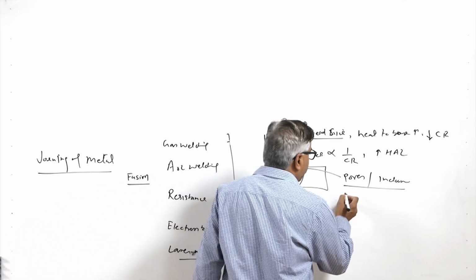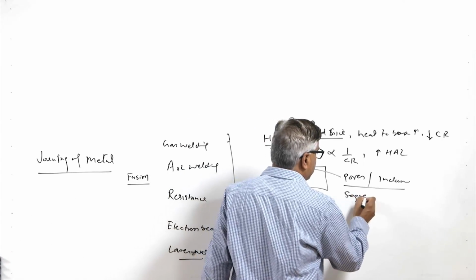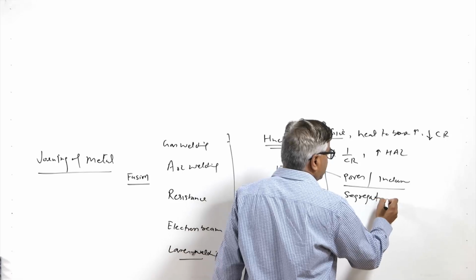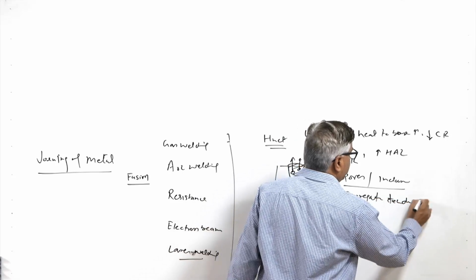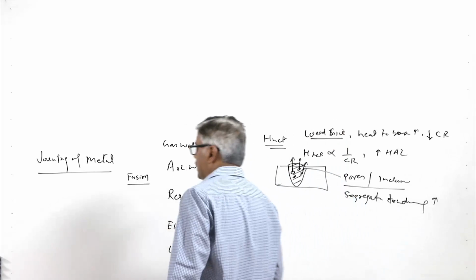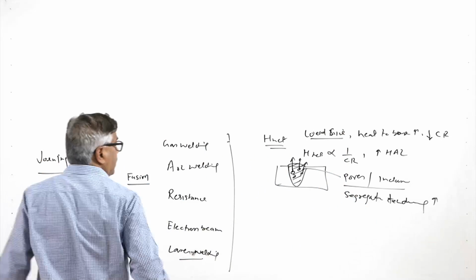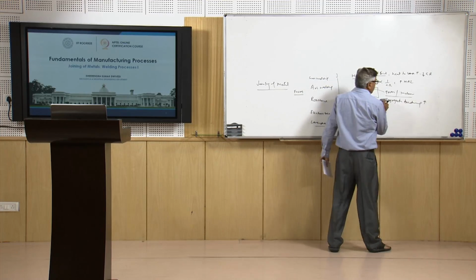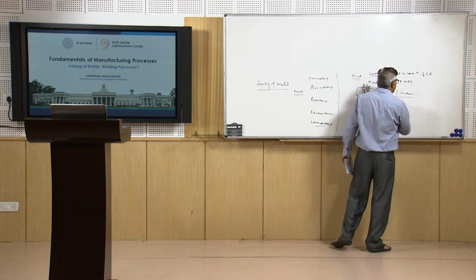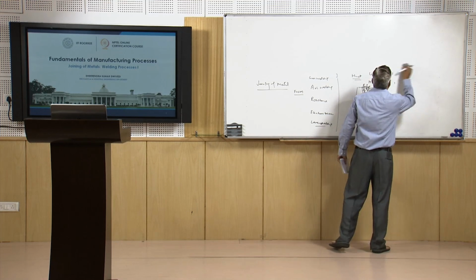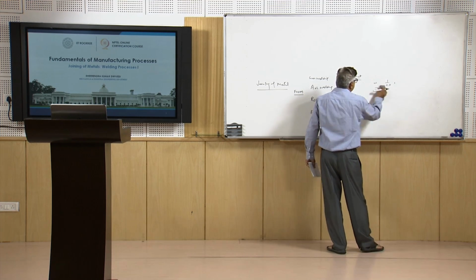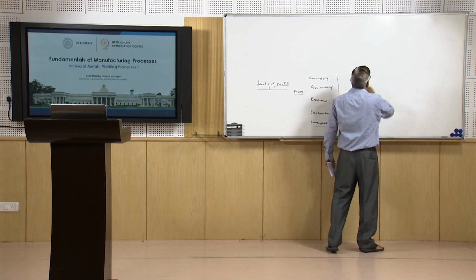At the same time, the segregation tendency, especially in the case of alloying elements, increases with the increase of solidification time and reduction in the cooling rate. So, these are some of the effects which are related to the heat input.